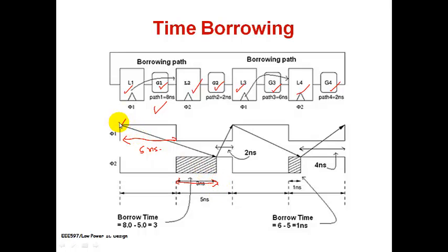So my computation for my logic L1 can start and it can extend further beyond the 5 nanosecond time what I have here, and it may go into 8 nanosecond totally, and this is the borrowed time from the next clock duration. And for the next operation I need to have only 2 nanosecond. So there is no problem when it is on. I would have that operation also getting completed. So my first job is done and my next job also is done.